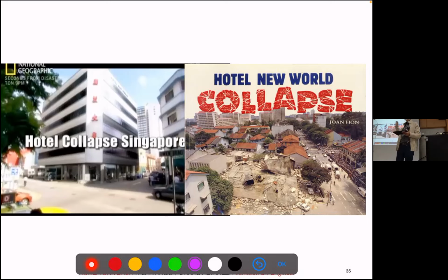So this is why I insist so much on cracks. To get this familiar, many cracks are totally innocuous, have no problem at all, but structural cracks, you have to have very clear in your mind those which are really worrying, right? And one column with cracks is always a problem, whichever cracks the column has, right? So call one expert, a real expert, right? Somebody who really knows, not those who say they know. Being the president of a big company doesn't mean you know a lot. Right? Go to the experts and make sure they know what they are doing and they give you the right information.